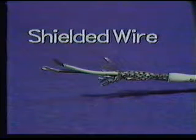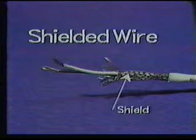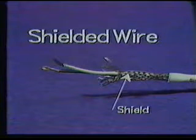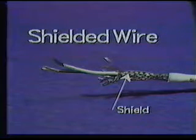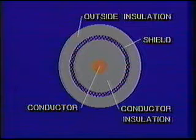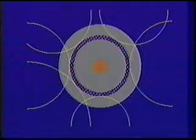Shielded wire has two important properties that make it ideal for this installation. The shield around the insulated conductor provides physical protection to the signal conductor. The shield also provides protection around the sensitive conductor to protect the signal it carries from being affected by induction. We learned that all conductors, while carrying current, radiate a magnetic field. The field's strength depended upon the amount of current flowing.